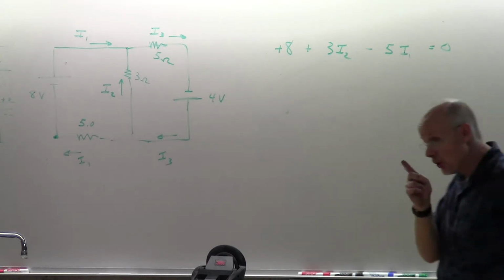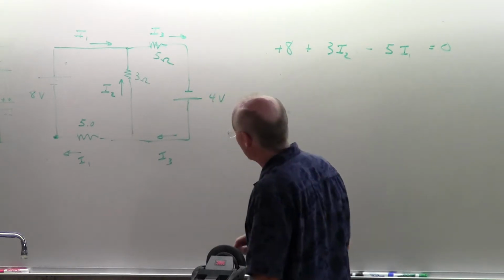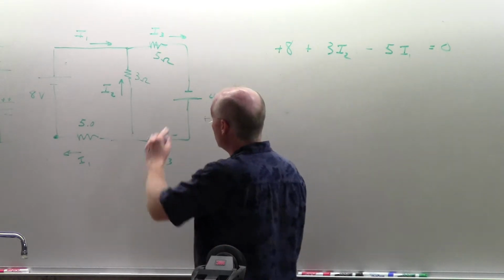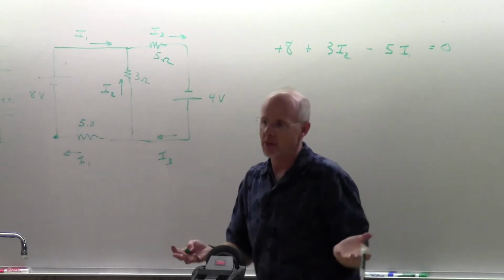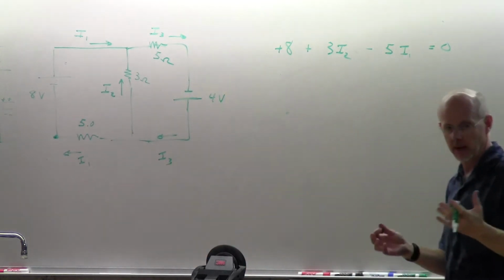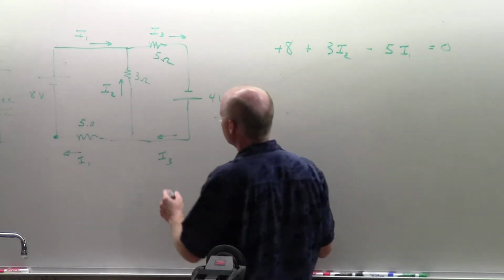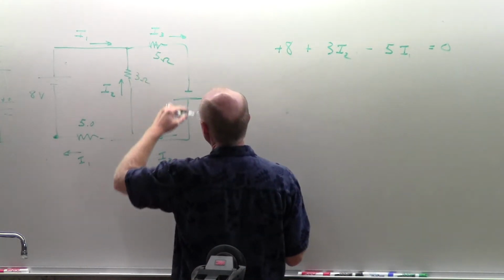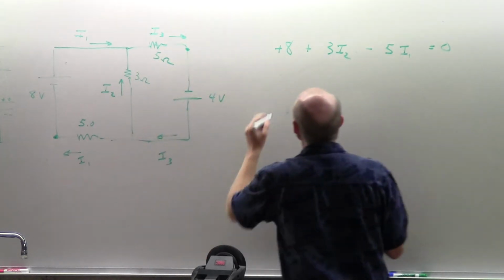That would be one of the 3 independent equations I need. I know I can get 2 independent ones because I've got 2 small loops. The question is, should I do the 2 small ones or include the big one? I'll do the 2 small ones, since it's probably the best way to explain making sure you get the independent ones. So I'm going to do this loop. Again, I'll start here and go across that way.